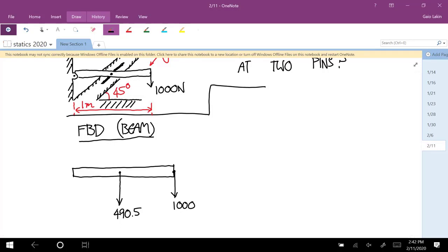And now there are two joints in this one. We have to think about the loads that each of those two joints applies to that body. So first, let's think about the pin on the left side. So a pin joint like that, is there any axis where translation is allowed by that pin? If you think of that pin as connected to the ground? No, that beam could rotate, but you couldn't move that point this way or any direction. Okay, so that means there's a full vector of forces applied by the pin.